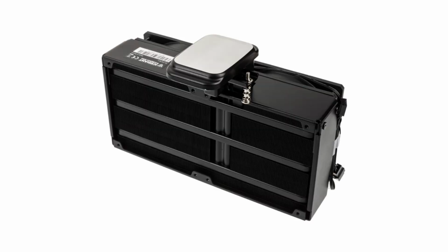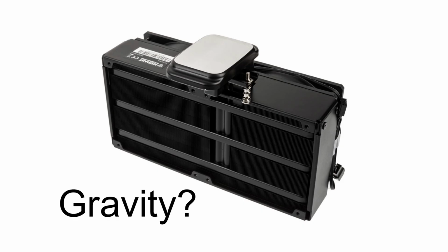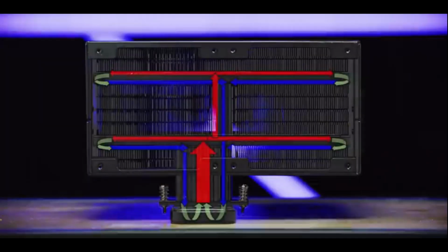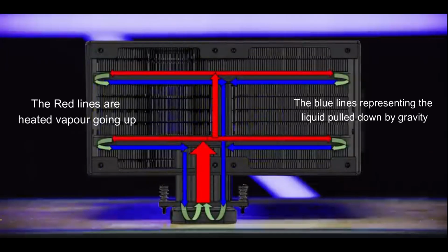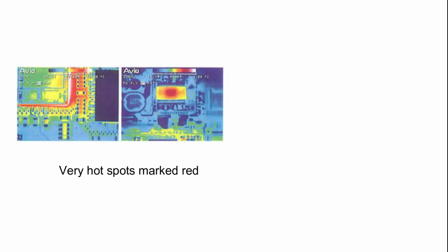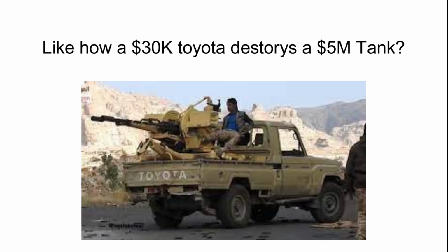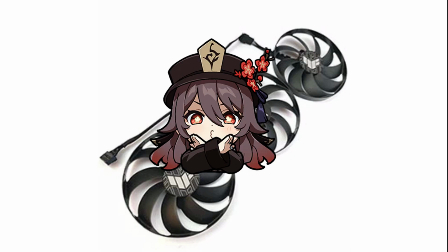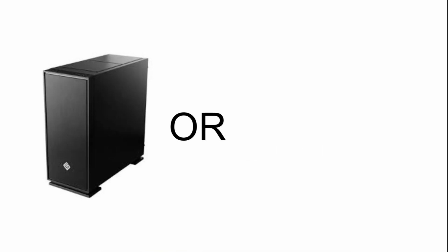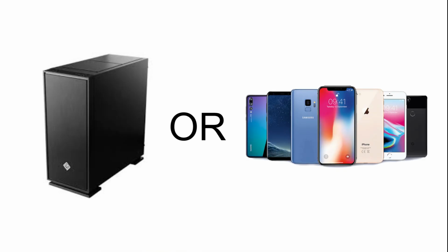But the thermosiphon uses gravity to pull down the vapor and turn it back into liquid faster, improving heat efficiency and lowering the chances of heat saturation. This means we can cool much hotter components silently with better reliability, which is a huge advantage for fanless designs like silent PCs or thin electronics.